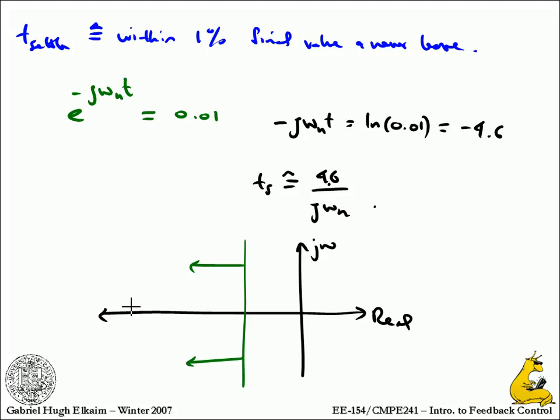Is this approximate only because that's specific to second order systems? As well, right? But if your dominant roots are second order, it's going to be pretty close. With all of these things, they get you close. So what you do is you put in your specs, you make your design, you simulate, and you say, okay, did I make it or did I not?